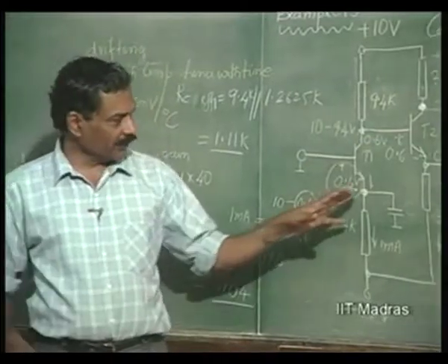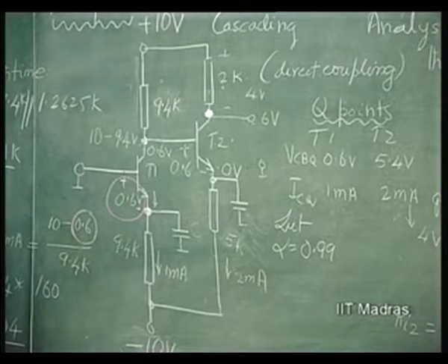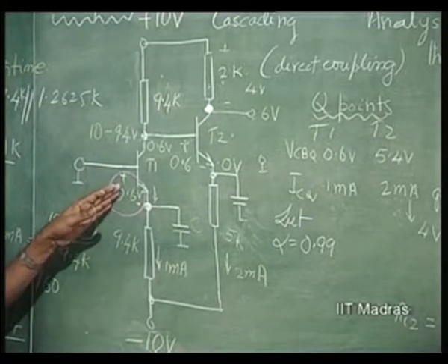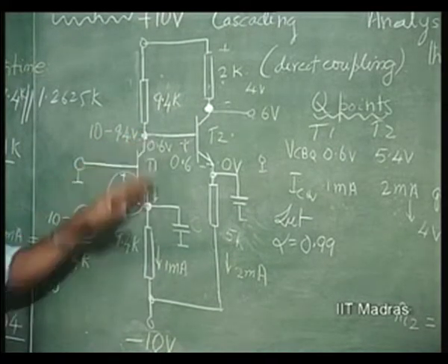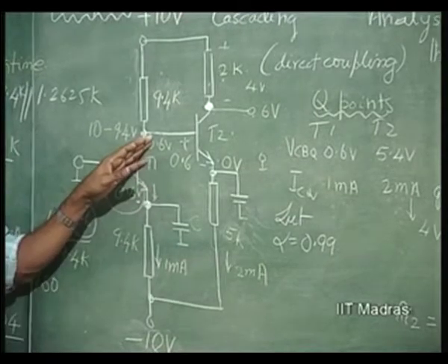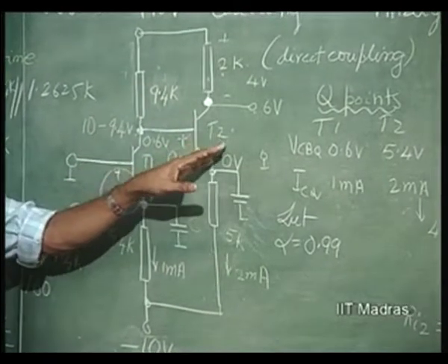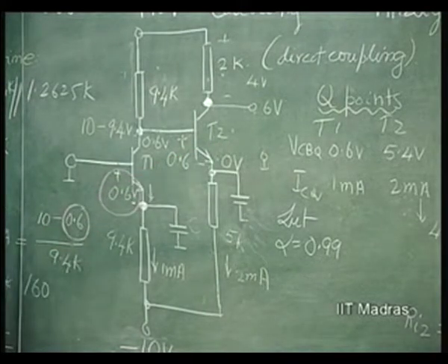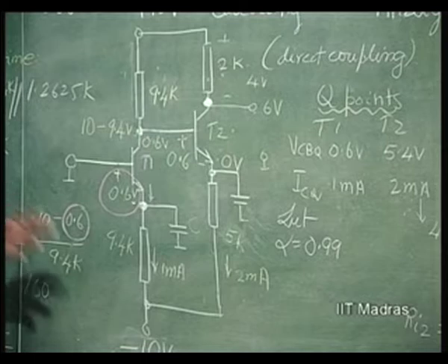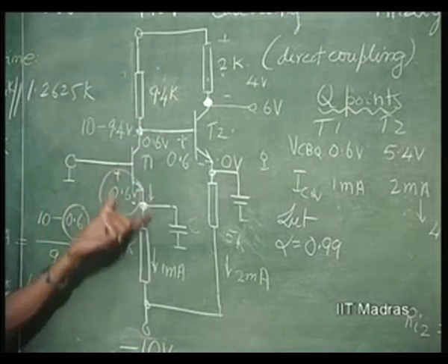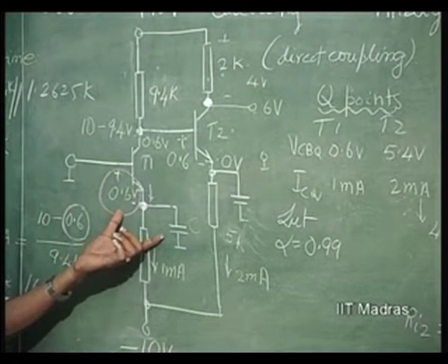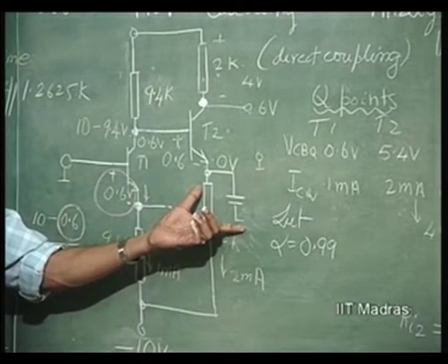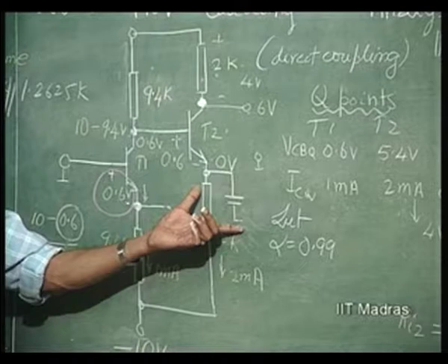One of the greatest disadvantages of such coupling is that if there is a DC variation here, that will be amplified here if the capacitor is large, and that amplification is further amplified here. If there is decoupling, these will be contained in the local stages, and therefore you can amplify without amplifying the drift component.